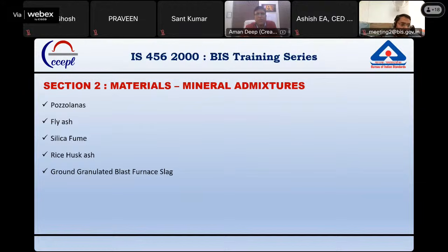When the hydration of OPC takes place, a lot of calcium hydroxide is formed in the chemistry of the hydration process. This calcium hydroxide, when it reacts with reactive fly ash, silica fume or rice husk ash, also forms a binding chemical and acts like cement.